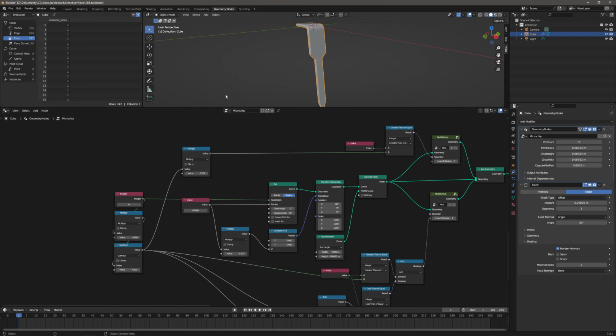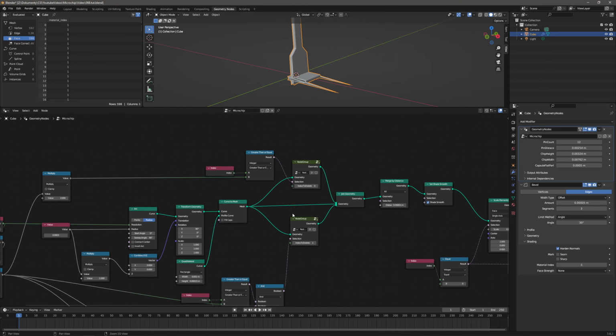8. Also, you can notice that the lower the number of the resolution, the bigger the angle. So you can also adjust it to your liking. Well, let's try a higher resolution, 24, and we are all messed up. Actually, not really. What we have to do is just flip the faces that we are deleting. So let's flip that to 1 and this one to 0.